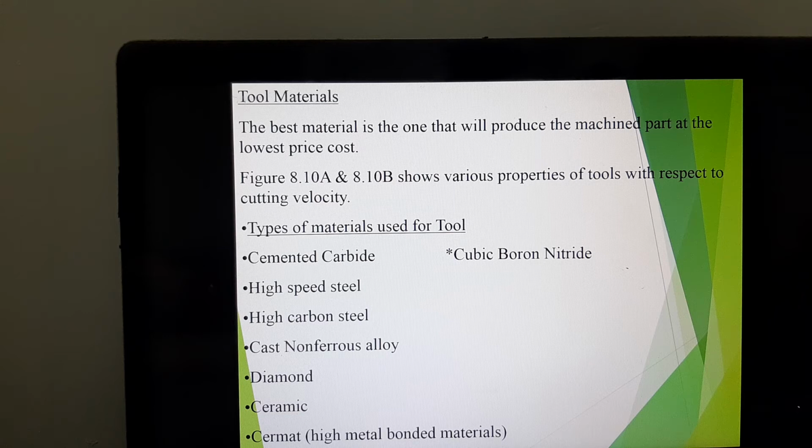When I say compatibility, one is compatibility in terms of hardness, meaning that when you use a cemented carbide or high-speed steel to cut these compatible materials, your cutting tool would not break. Number two, there would not be any chemical reactions between your cutting tool and material of cut. Very important. You do not want to alter your material.